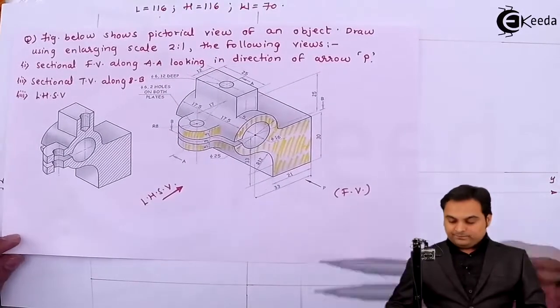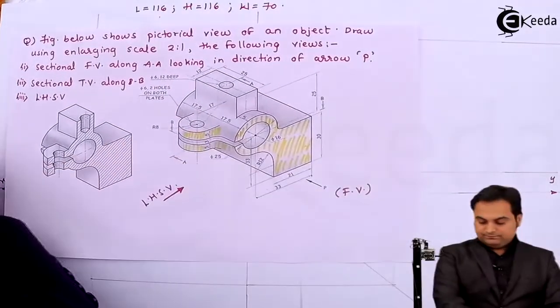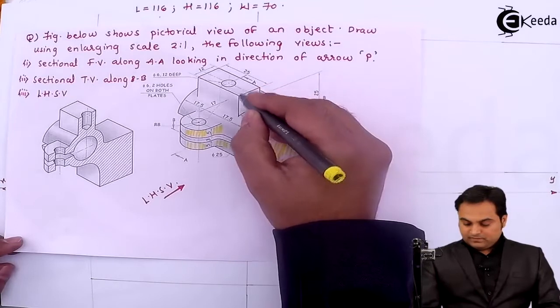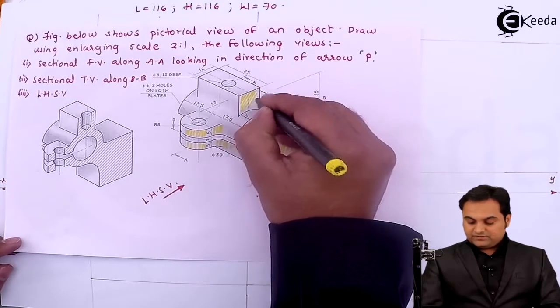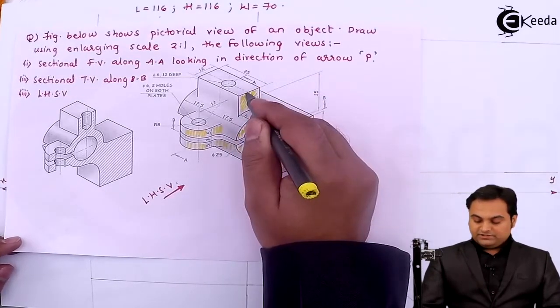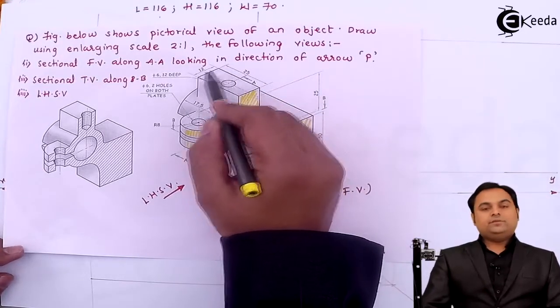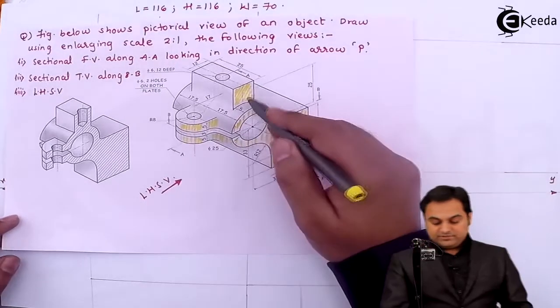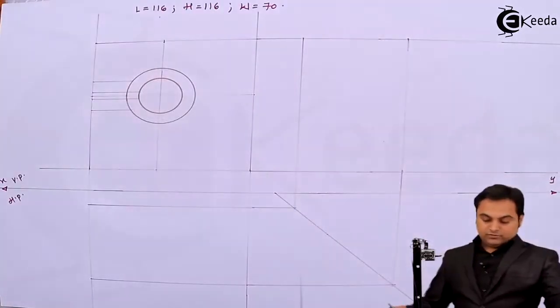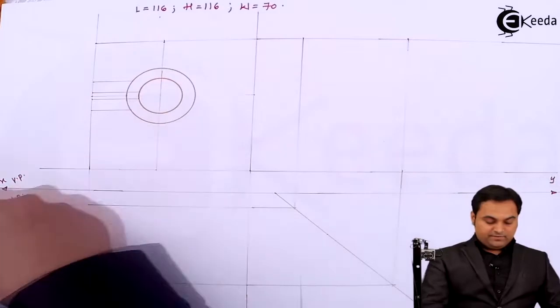Next, looking from front, even this portion, this rectangle is visible. So from the center, here if I see its total length is 12, so this will become 24 for us and it is measured from the center. So from the center, I'll take 12 mm on both sides.